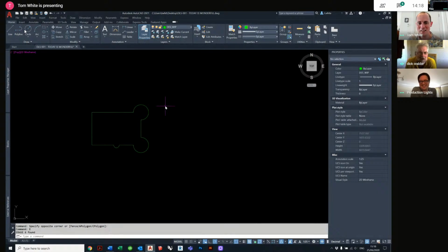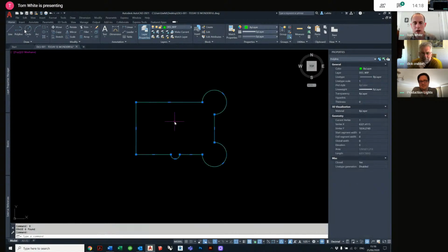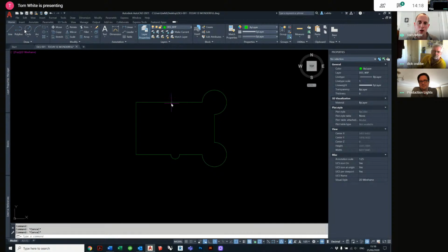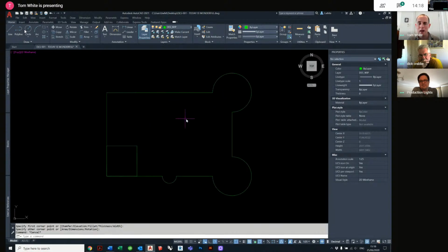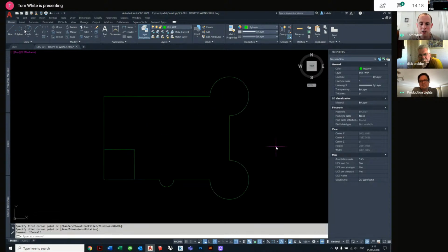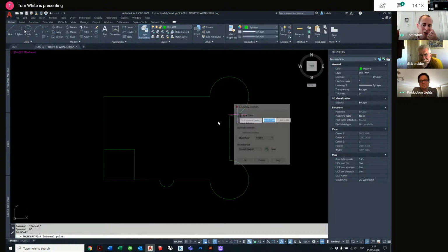So that's the kind of thing that you might use if you've got a wacky reception area or something with carpet. That's the kind of command you'd use to turn it into an entity. I know the scale for this is really, really small, but for example, this is the boundary of our space, and Dom says, let's put a control area in the corner of the space, and the production manager said, well, how much carpet? So if Dom's taking up this corner in the side, how much carpet do we need to fill the rest of the space? A quick way of doing it is the boundary command and enter.